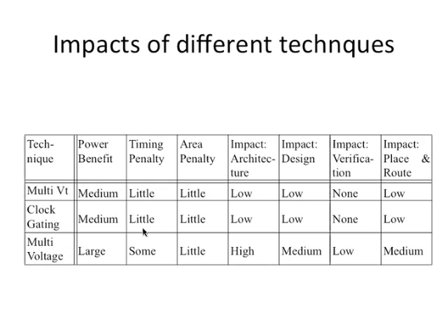There's no timing penalty pretty much with this clock gating, very little area penalty, and you don't have to change anything in your chip. You don't have to even think about this. Nowadays it's pretty much in the back end, right? When you're writing your design in RTL, Verilog or VHDL, you don't even think about clock gating. The tool basically takes care of it and puts it in, and it's a very simple technique which is widely used.